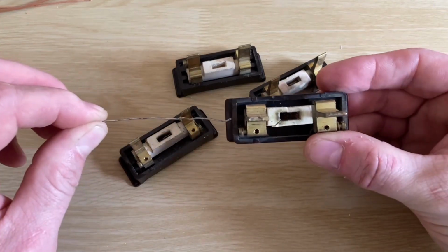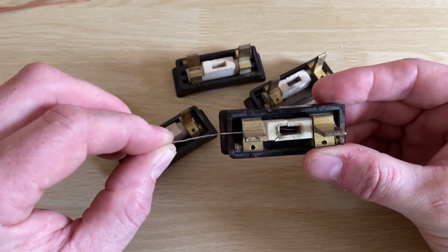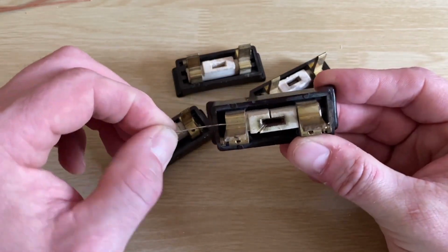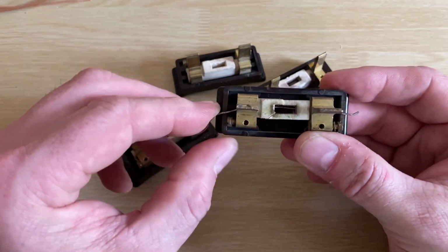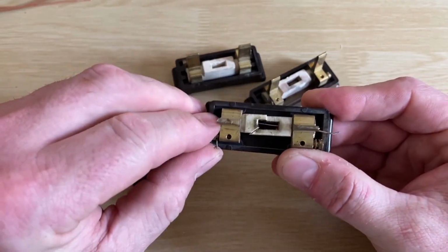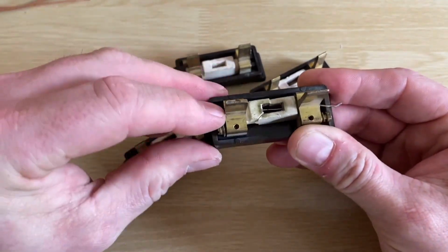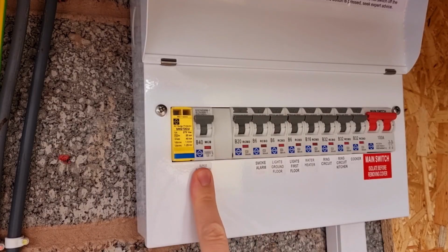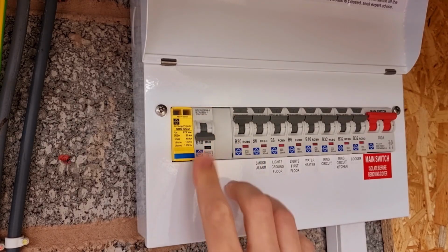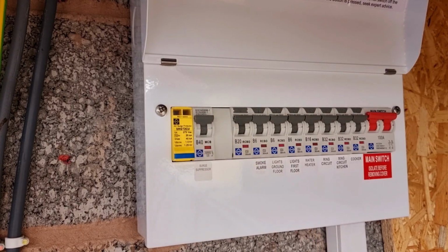To prevent this from happening, we provide overcurrent protection. This used to be in the form of a fuse, which was like inserting a weak link into a chain, in that a thin filament of copper inside the fuse would melt when too much current flowed through it, thus disconnecting the circuit. Over time, this was superseded by the circuit breaker, which had a mechanically operated disconnection system and had the advantage of being quick and easy to reset after it had tripped.